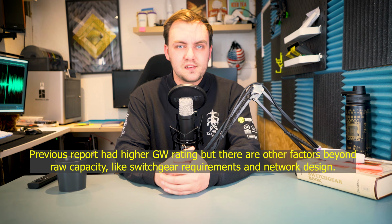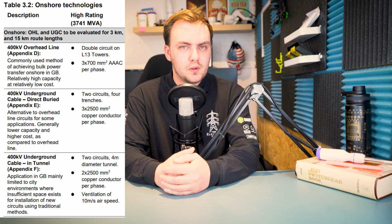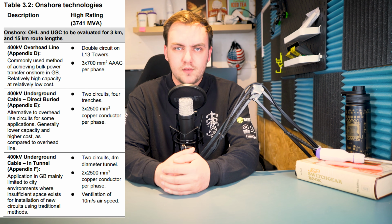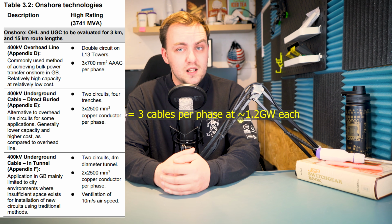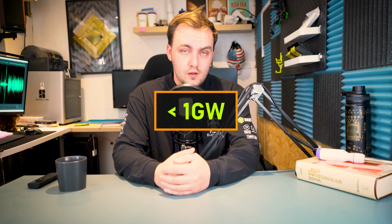While overhead lines at 400 kV can carry 3.6 gigawatts per circuit, a 400 kV underground cable typically carries only 1 to 1.5 gigawatts per circuit, and that's with ideal soil conditions. In hot or constrained areas it can drop below 1 gigawatt, but with forced water cooling you can push that up to around 2 gigawatts, but that becomes expensive and complex.